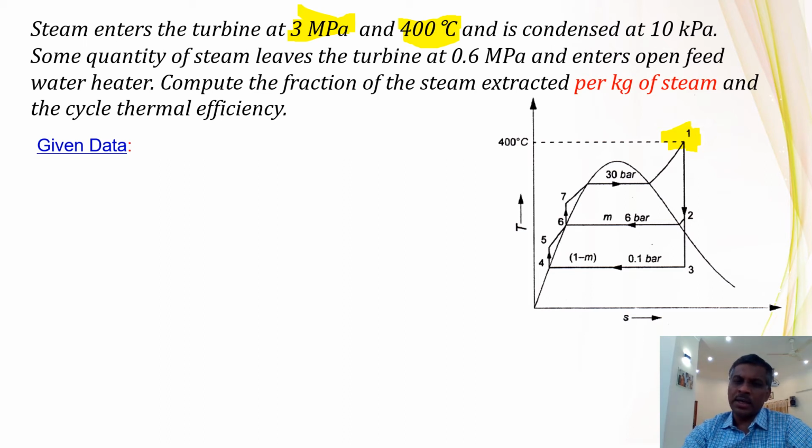I recommend that you use a Mollier diagram again to make it easy, make it fast, and you can avoid errors because you don't consume much time, at least to calculate H2, H1 and H3. These 3 points you can straight away take from the Mollier chart. That is what I will recommend. But you remember the TS diagram. That is easy.